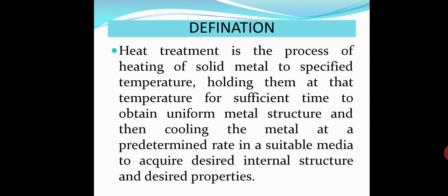Heat treatment is the process of heating solid metal to a specified temperature, holding it at that temperature for sufficient time to obtain a uniform metal structure, and then cooling the metal at a predetermined rate in a suitable medium to acquire the desired internal structure and desired properties.